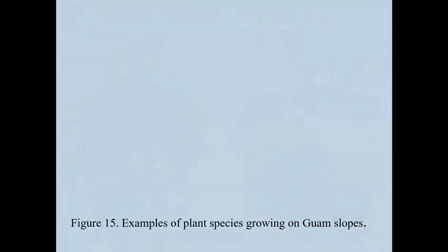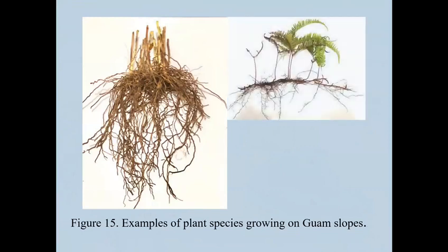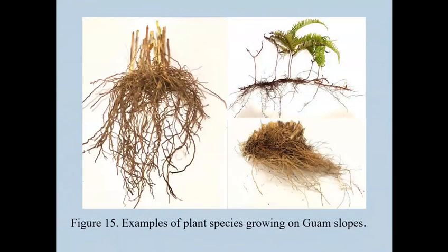To further evaluate reinforcement offered by roots in soil stabilization, we are looking to test more plant species such as shrubs, ferns, and grasses with varying root diameters and depths for tensile strength and root area ratio. We also plan to measure the resistance of root structure to being pulled out of the ground, also known as a pull-out test, and compare the results to the root tensile strength measured in the laboratory, so that we can analyze how root tensile strength affects soil shear strength.